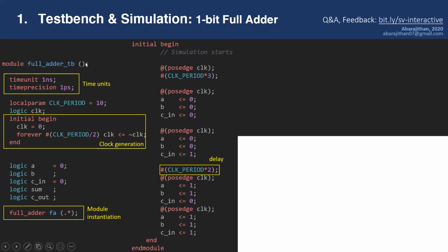Why? Because we are not connecting the test bench to anything else. The test bench is a fully self-contained thing, and inside it we create and give the signals. It's not synthesizable. The port declaration is empty, so we are not telling input, output, or anything.